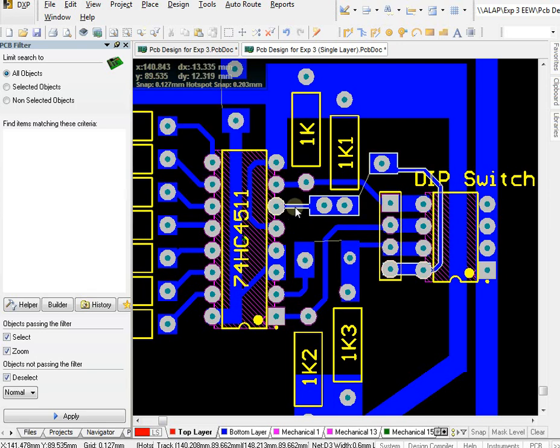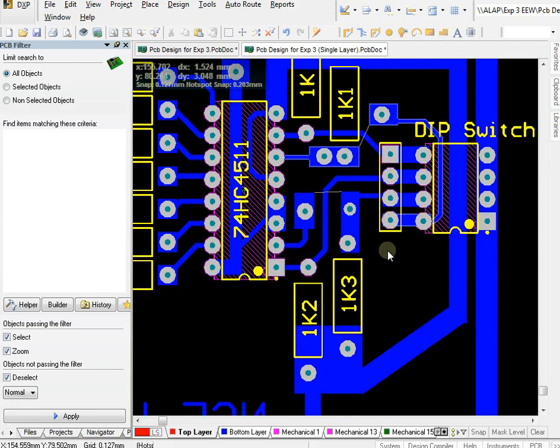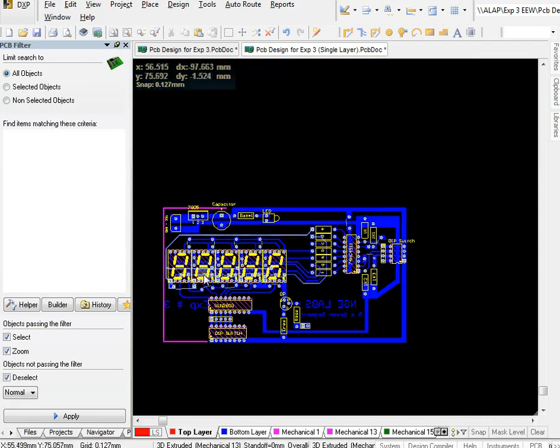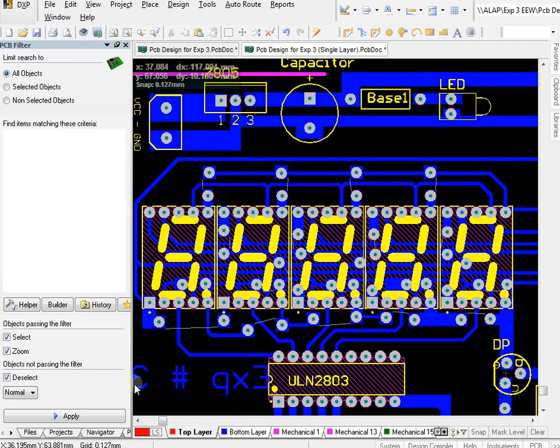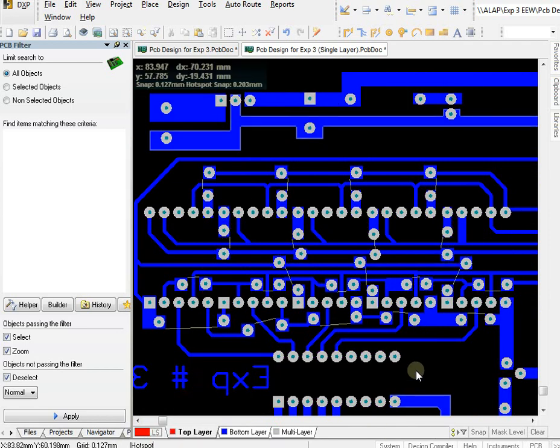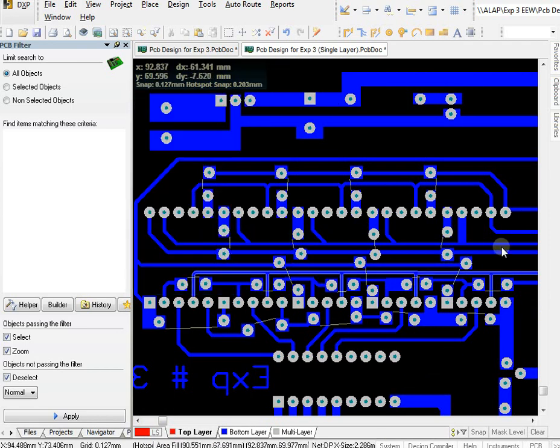Secondly, I can have from this hole to this hole, because there is already a track flowing in below, so I cannot take that track. For that one I will require second layer. So this is going to be connected here like this, and then if I move on towards the other area, here the important thing, let me just change it to single layers. You can see what I have done.